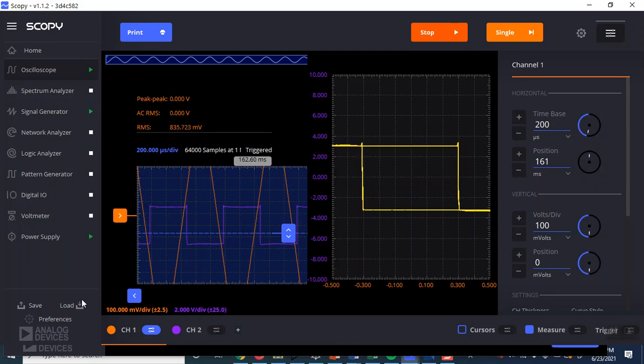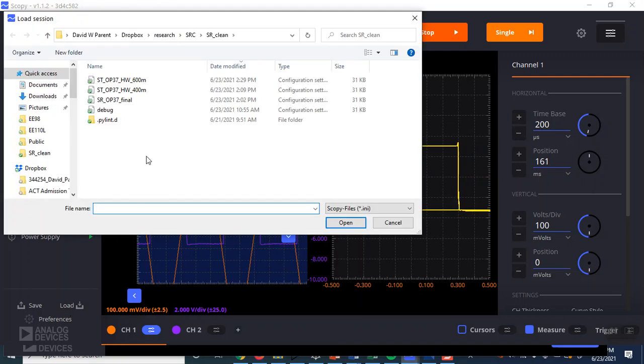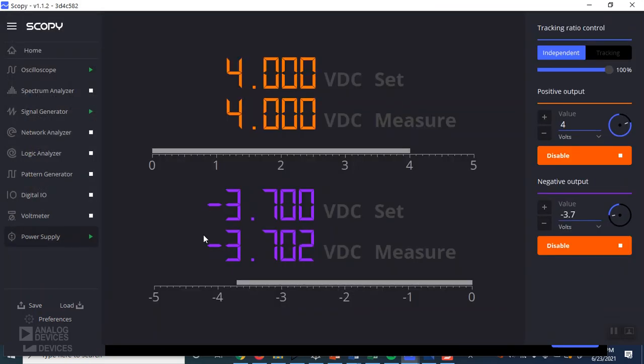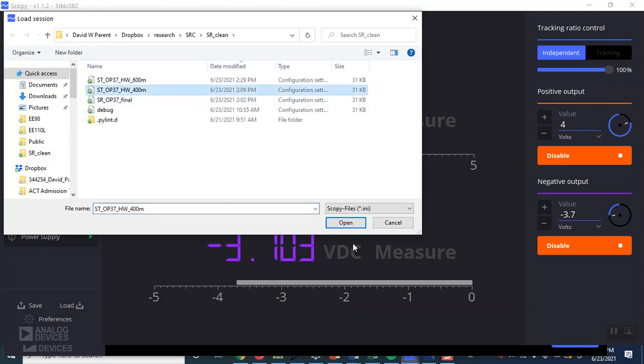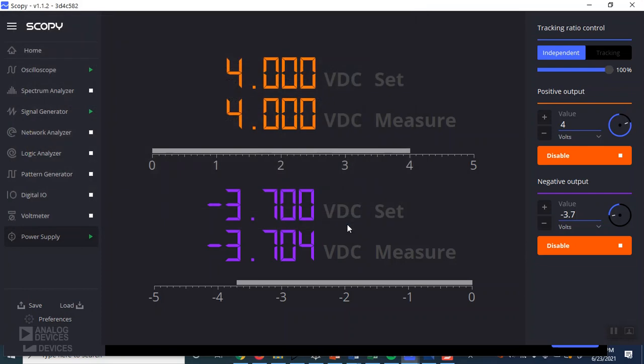Now, I have links to this one. That should set up the hysteresis width of 600 millivolts. Now the thing is, more than likely you will have to adjust these to get it into that system. And for the group that's doing 400 millivolts hysteresis width, it is 3 and 2.6.